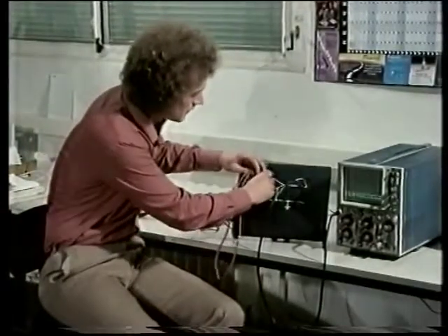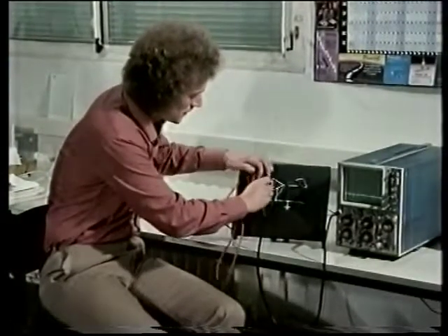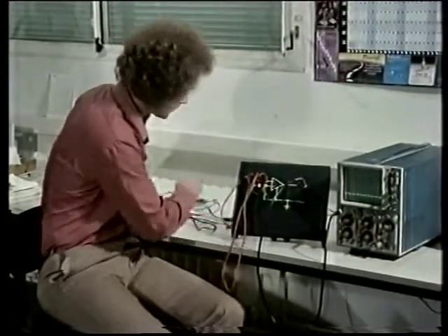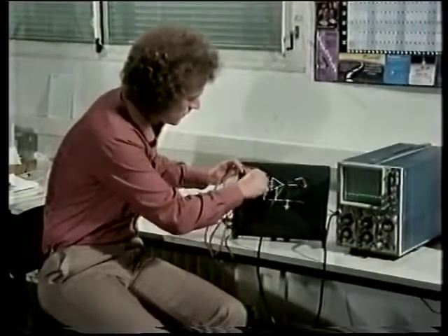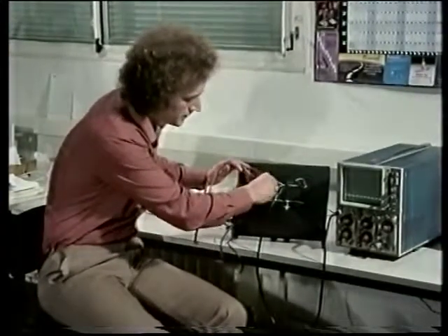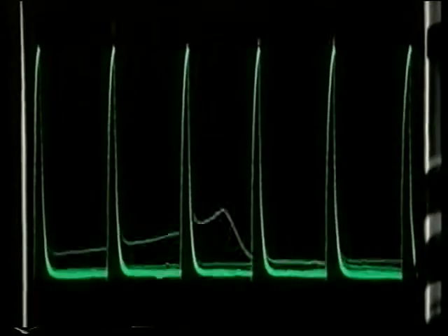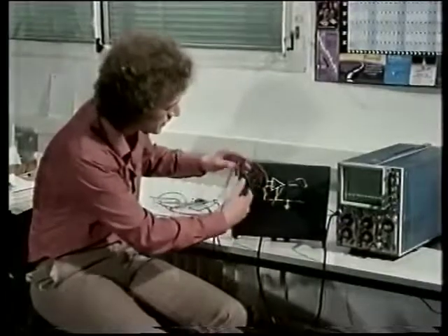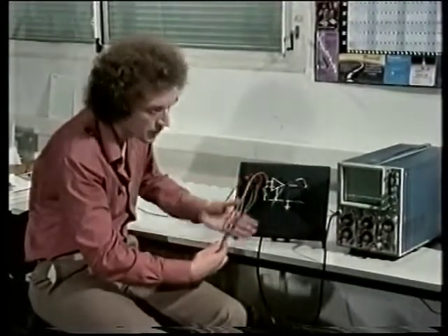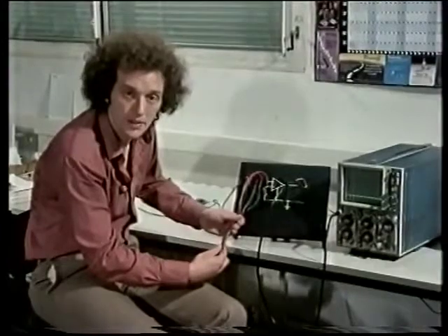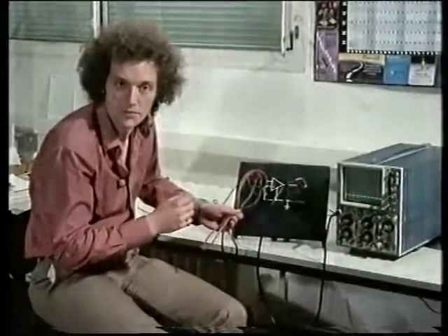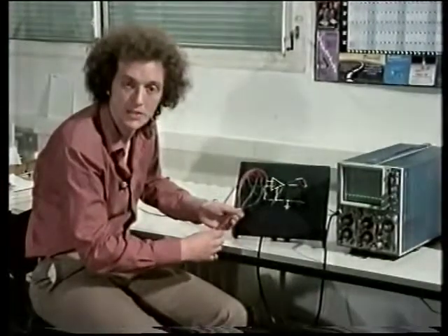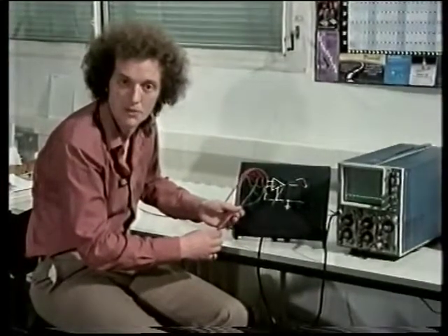So let's disconnect this earthing wires and connect straight across to the non-inverting input. And I think you can see there that we've got an improvement already. But we'll get a better improvement if we hold the two wires together. And the reason is that the amplifier only amplifies differences between the two incoming signals. So if we can physically keep the two connecting wires close together, the pickup should be the same on both.